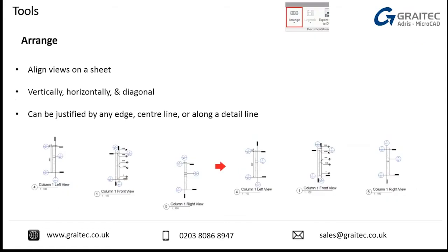Again, another really, really cool tool when it comes to documentation and putting our drawings on sheets. If we want to arrange views on a drawing sheet, that was added in about 3 or 4 years ago now, we have the layout grid. So we can put a layout grid on top of our title block, and then we can use that to align our views. It can work, but maybe we could be more automated. So the arrange tools will actually allow us to align and arrange our views on drawing sheets automatically.